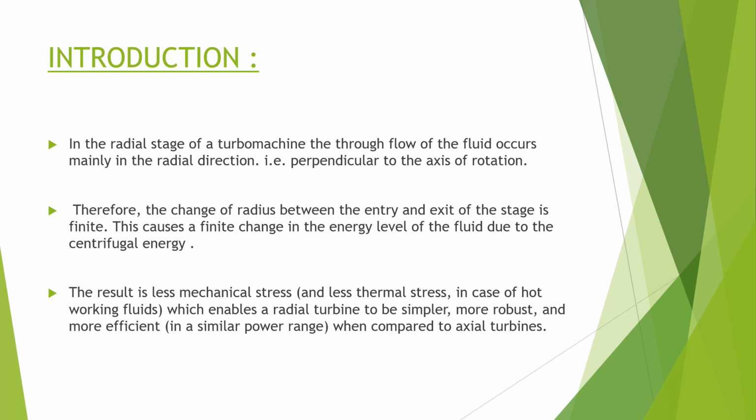The result is less mechanical stress and less thermal stress in case of hot working fluids, which enables a radial turbine to be simpler, more robust and more efficient in a similar power range when compared to axial turbines.